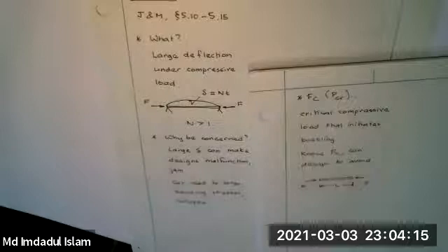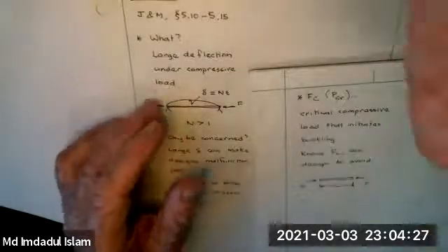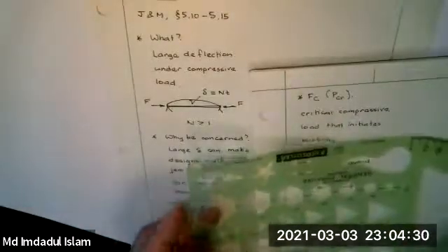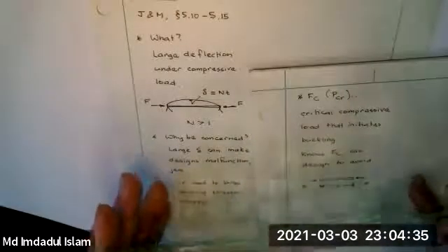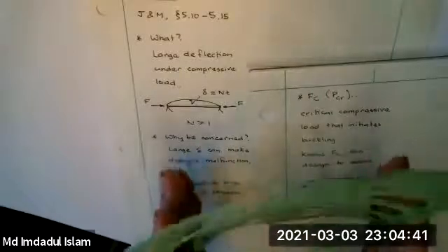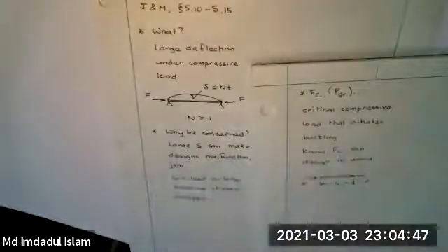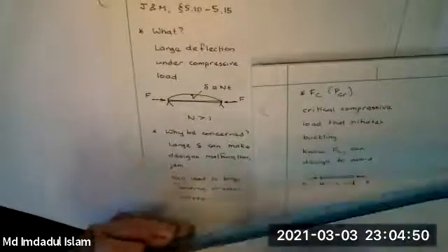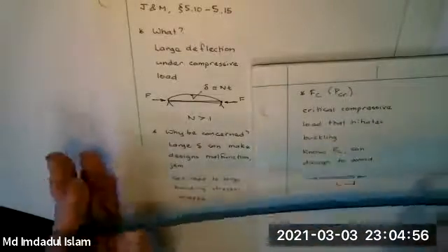Well, the longer this beam that's under compression gets, the easier it is to buckle. What I'm saying is, this is a very funny looking thing to buckle, and it buckles very easily that way. But if I put it this way, I can feel it's a little more force, and you can do any of these demos yourself. But if you want a more graphic example, this is a beam this way because its length is relatively big compared to its thickness, and I managed to buckle it.